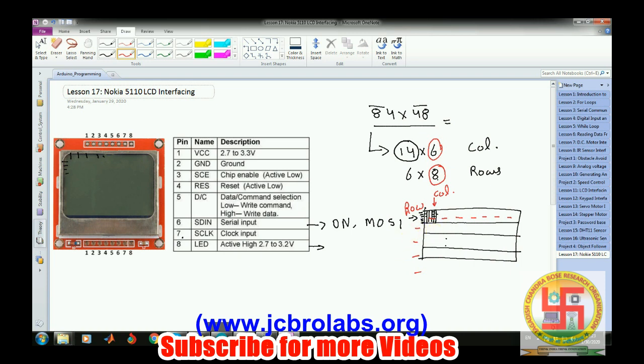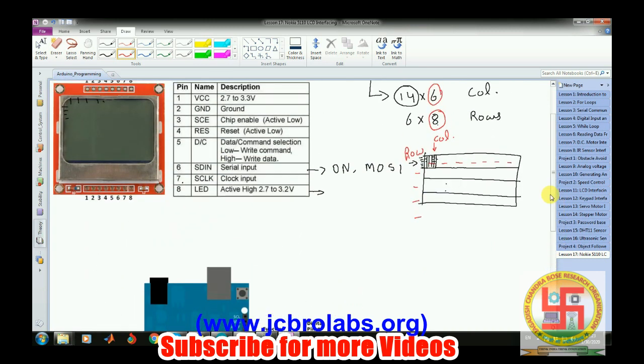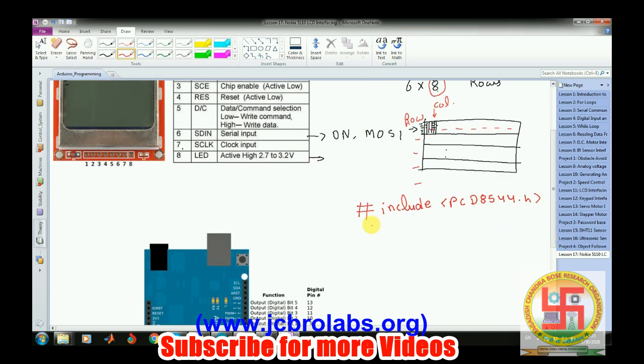Now there are some header files which have to be included. The header file which we are going to include is the Adafruit PCD8544.h file. So this is a driver header file which is used for displaying characters on this LCD. Now there are some functions associated with it, and those are very straightforward.